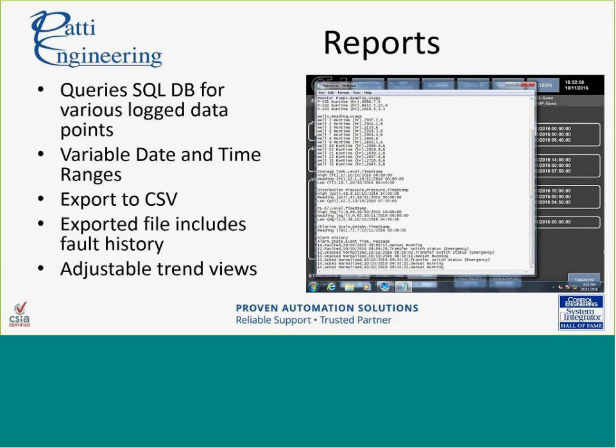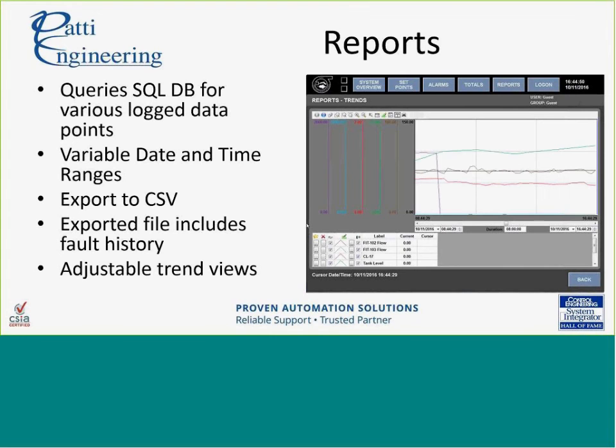And then we also embedded the alarm history into the report. That way they could track which alarms happen more often, Pareto those, and kind of focus on the bigger offenses. We also utilized the trend screens and allowed a lot of optimization and modification in the runtime. So they can turn on and off different pens, different process values, as well as zoom in, zoom out, change the set point, change the windows that you're looking at.